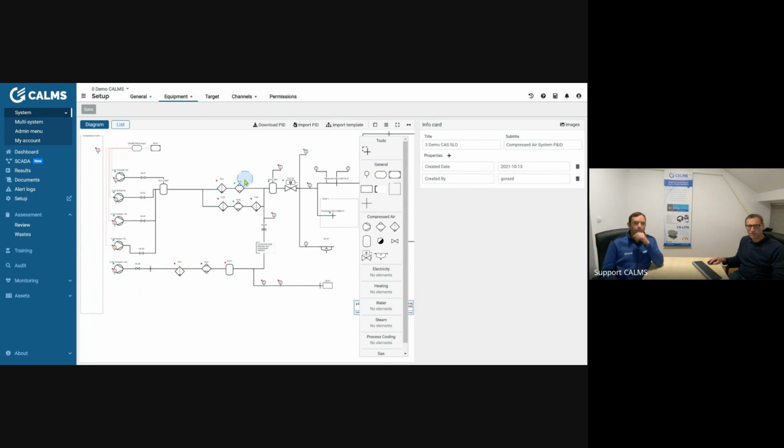And those dryers and filters, do they have a separate bypass, or not? They have a separate bypass for each dryer and filter. No, it's just one single bypass. One single bypass for the complete air treatment, for both dryers here in this room. Okay, we will draw this later, and this is your 4 cubic meter receiver.